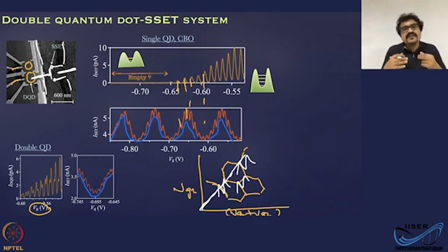Second thing is single electron transistors themselves are Coulomb blockade devices, so the charging and discharging events in that device can actually affect the system that you are trying to probe, because you are trying to probe the oscillation in the potential energy due to charging and discharging events, right? But the sensor itself has that oscillation, and so this can actually act back onto the other system too. So there is an extra piece of interesting neat physics there, which we will try to touch upon in one of the coming lectures. All right, okay.